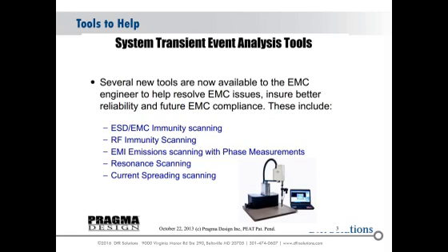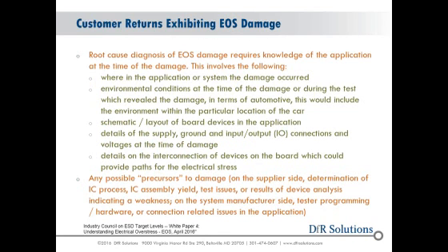However, there's never been a good debug tool or tool set available for ESD, other than the ESD guns and ESD pulse simulators to try to break the thing. So the new current reconstruction or current spreading, resonance scanning, and ESD susceptibility scanning now provide parallel type tools to easily find the hot spots and problem areas that can lead to root cause. So I guess you want to take back on the next one.